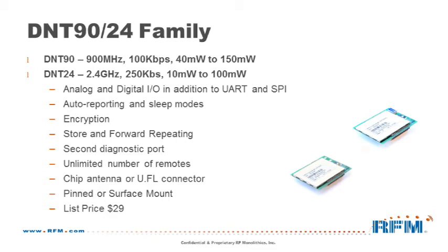Again, we have analog and digital I/O with UART and SPI port. It has auto reporting and sleep modes, and it has encryption. It has AES-128 encryption. It doesn't have the authentication. All right, so that's one place where we're able to reduce the cost a little bit.